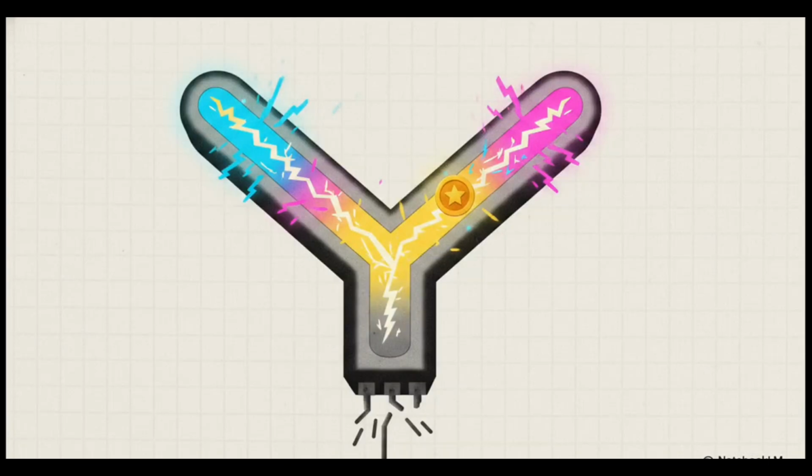Now, what we're actually sculpting with all that lithography are millions and usually billions of microscopic switches called transistors. Specifically, modern computers use pairs of these called CMOS. Think of these transistors as tiny electronic gates. A high voltage, like maybe 3.3 or 5 volts, opens one path. That represents a binary 1, or true. A low voltage, basically 0 volts dropping to ground, opens a different path, representing a 0 or false. So when you add those 8 coins in your game, at the very bottom of your processor, it's really just tiny physical gates routing electrical voltages.